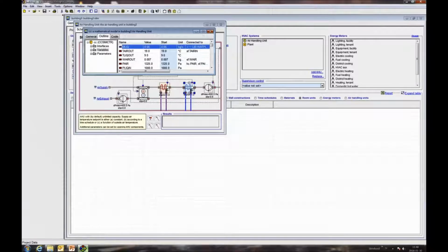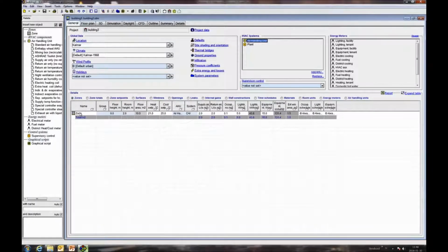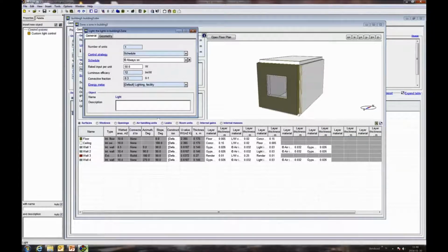I don't have time to explain this in detail now, but the main point here is that the total heat emitted from occupants will be equal to the given metabolism, which wasn't always the case before. And I want to clarify that this change only applies to the calculation of heat emitted from occupants. So the calculation of PMV, PPD is not affected.